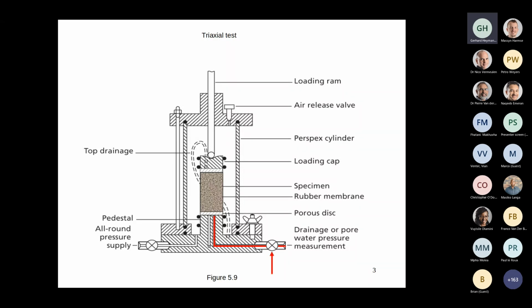Now, a bit of anecdotal feedback. Once in a while, I get a phone call from one of the laboratory managers saying, I've just received this sand or silt or whatever specimen from a client, and this client is asking me to do unconsolidated undrained triaxial tests. And I go, oh, now you have a dilemma, because your only option now is to go back to the client and very diplomatically explain to the client that it is not possible to do it.